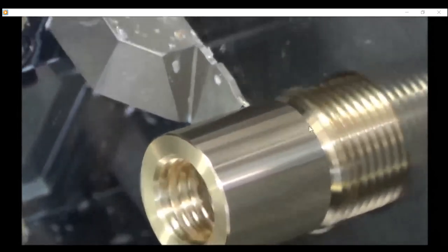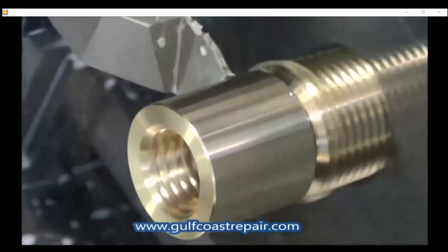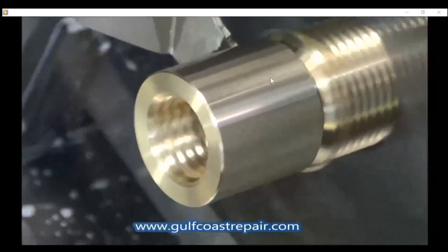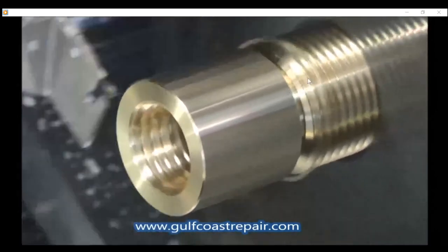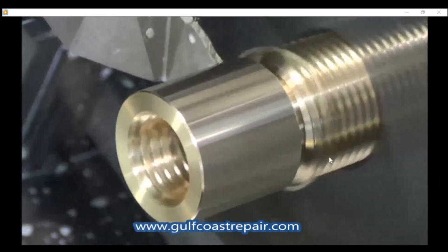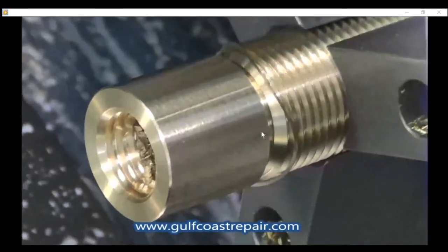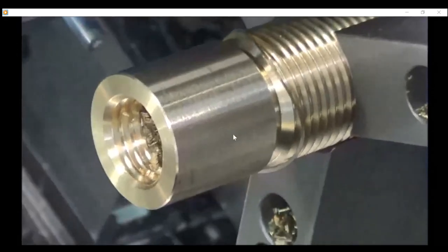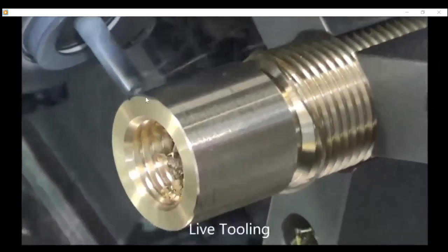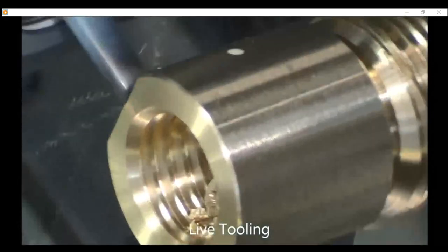This is the groove. We're creating a groove. Only groove. We don't want the cut off, but here we use it to make just a groove. You just make a groove here to separate this one from this one. That's it. If you penetrate more you cut, but you don't want to cut, just make a groove. Then this one is still remaining there. This is another multiple point cutting tool. I will discuss this later.